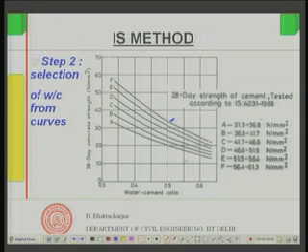For example, curve A represents 28-day cement strength from 31.9 to 36.8 megapascal, whereas curve B, which would be the next curve, represents a cement strength of 36.8 to 41.7, and the next one is 41.7, etcetera, and the last one is 56.4 to 61.3. This is what is more important. The first curve that we just discussed is a curve which relates for all cements without distinguishing between cement strength.